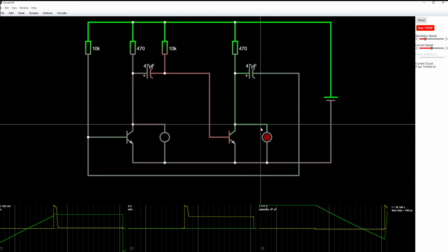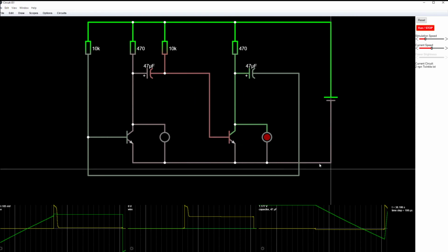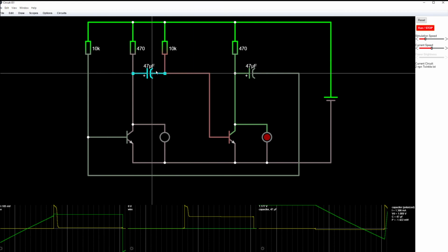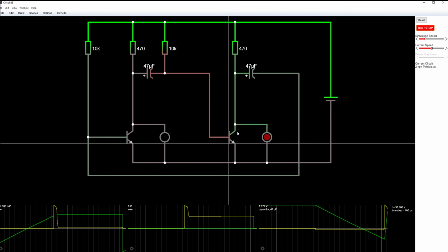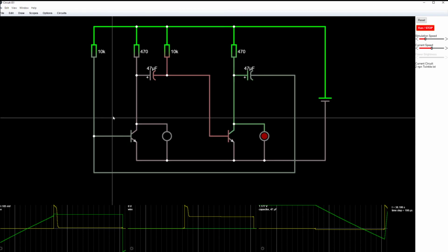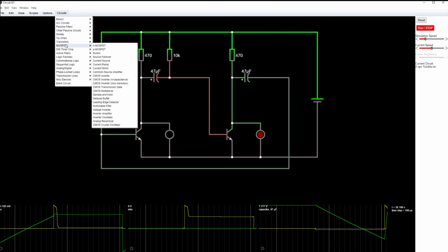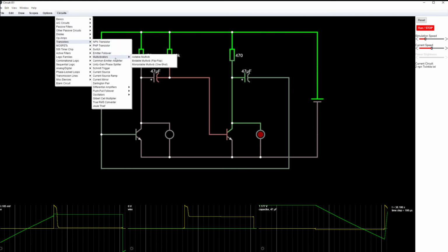Our triple circuit is just getting a third one in the line, so you can just get another LED and use the same technique with the capacitor. So the whole point is the capacitor is charging up, changing the voltage difference between the positive and negative end, and it's just using that to activate a transistor. This is also called a multi-vibrator.